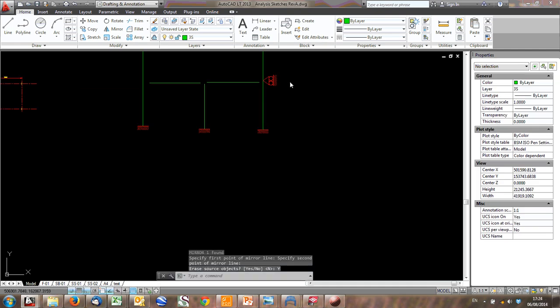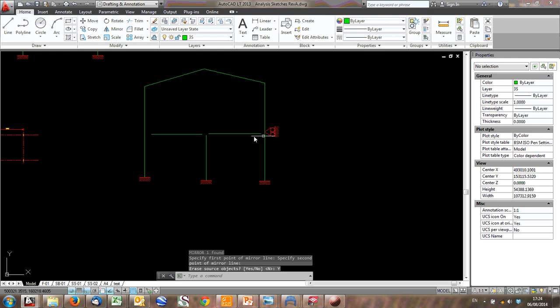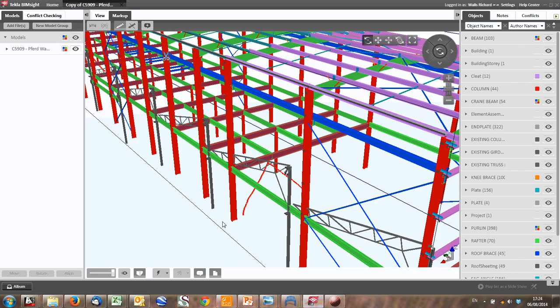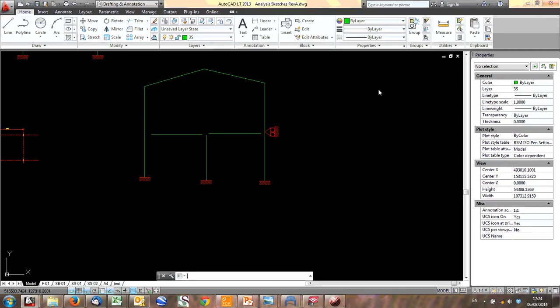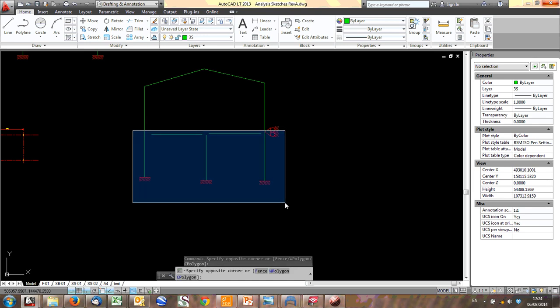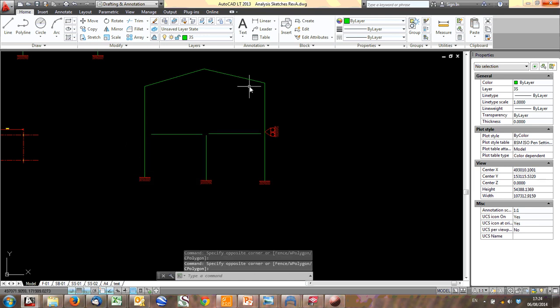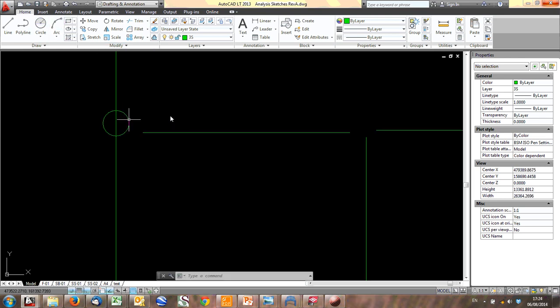You add a prop, and this is a force that you then take all the way down to the bracing that is here, that I've just drawn in, and here. And in that way, you can stabilize the structure. And you can use diaphragm action, a diaphragm of the floor here, to stabilize this entire structure. And especially, I mean, if this was, let's say, a concrete structure here with a steel structure on top, it'd be the exact same story. What you might just add in is a pin here, and a pin here.